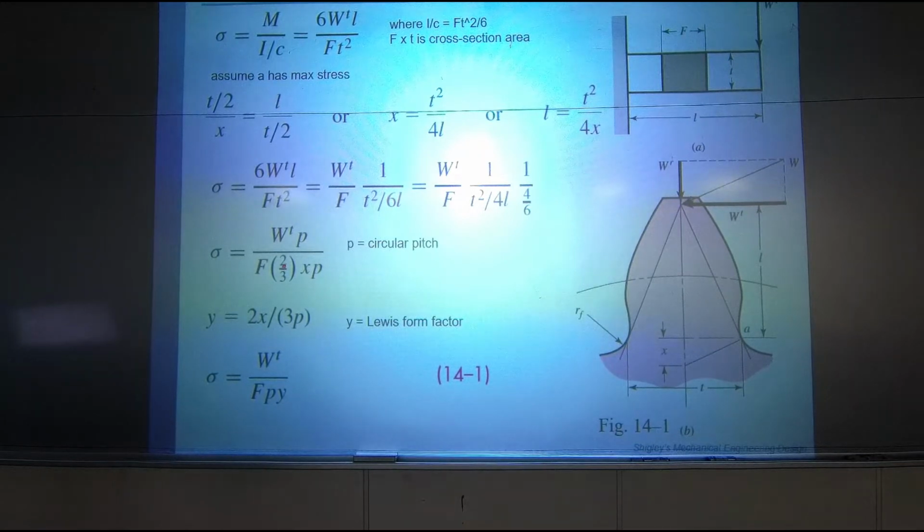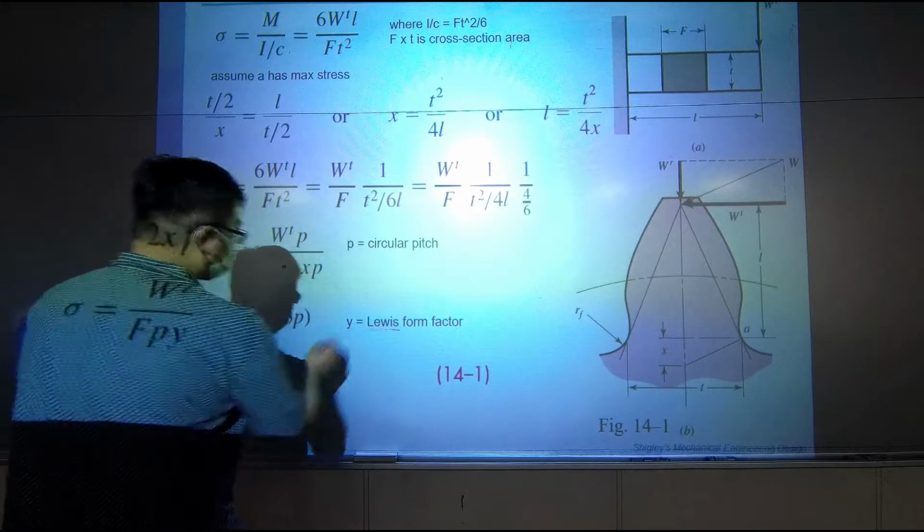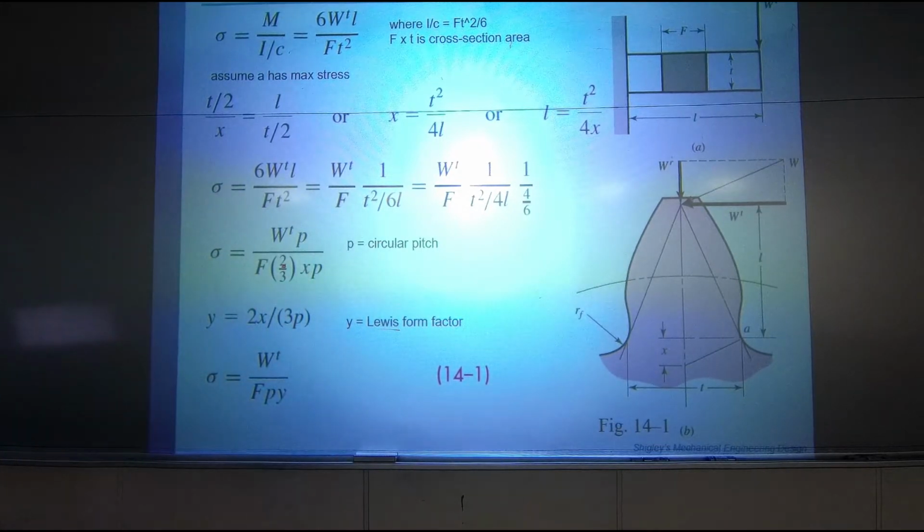So what happened is, there's a guy called Lewis, okay? He formulated this kind of model to simplify the force analysis inside one tooth of a spur gear. He derived general equations for the force analysis in each tooth.